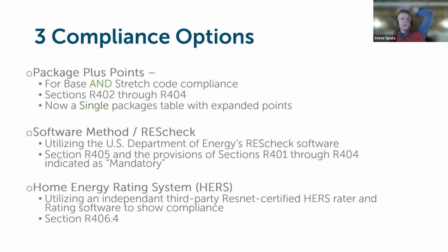The way the code is written, you need to show technical compliance, meaning that you've built a building or retrofit a building that meets the technical specifications of R values, U values, sizing for equipment, details for air sealing and building envelope air tightness, etc. All of that is the functional details. And then you have to show how you've complied with the code, the reporting side of it, through these 3 options that are available.